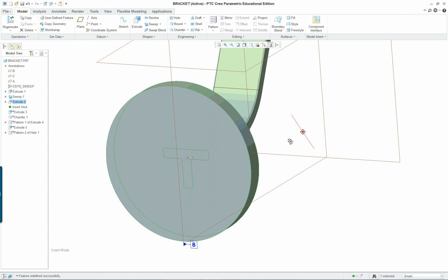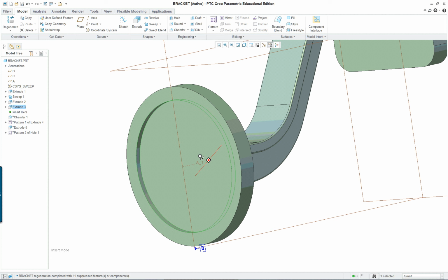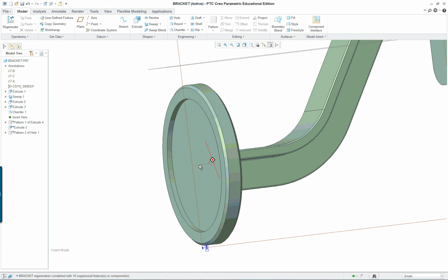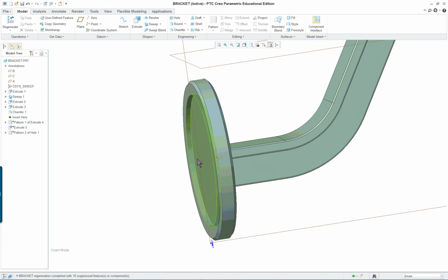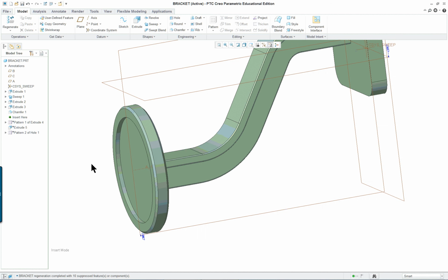We'll complete that one. Now, next one is a cut. And again, it's just a circular cut in from the face back in. And we have a chamfer on both ends. So you have two selections there. You select the front edge and then the back edge. They're identical.